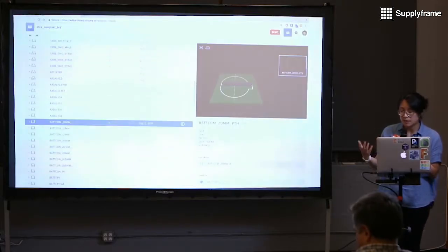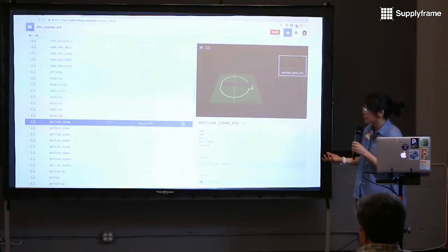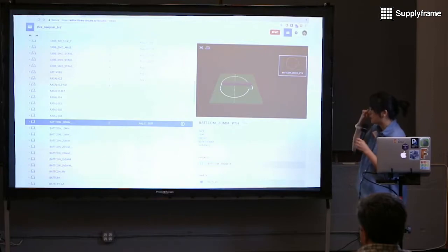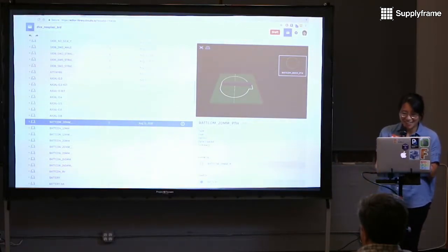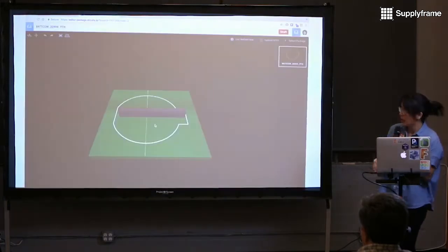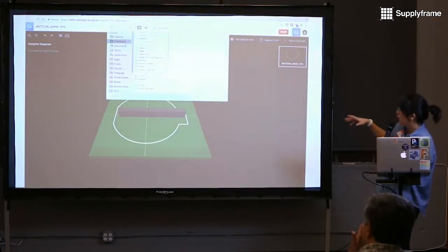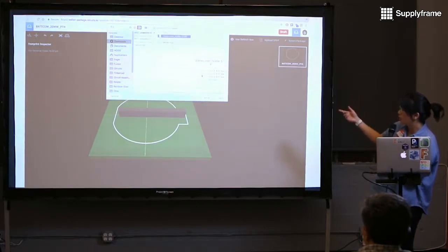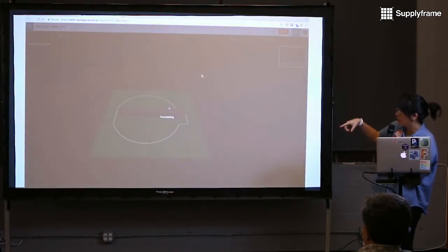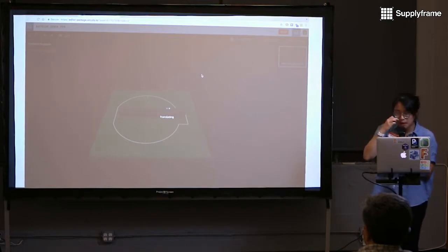And basically, for every footprint in your Eagle library, we generate a 3D package. And Chris actually did some fantastic work on that, as one of our developers here. So essentially, you can open up any of these packages and upload a STEP model, and then start to associate the relationship between the footprint and the 3D model.